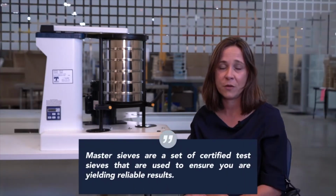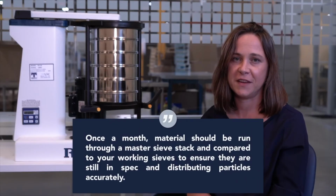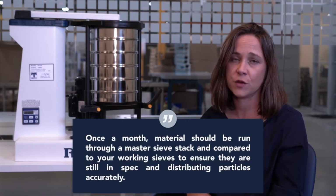As promised, here's your extra tip. To ensure that you continue to yield accurate sieve results over time, we recommend having two sets of test sieves. One set will be your master set, while the second is your everyday working test sieve set. Master sieves shouldn't be used every day. Instead, think of them as an insurance policy. We recommend using them once a month to make sure that your working test sieves are still in spec.